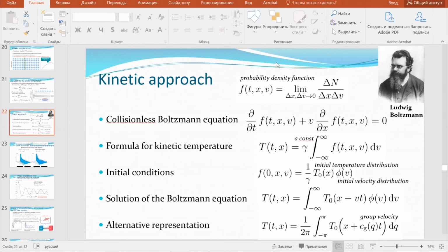You take the group velocity from the equation which we took from the long wave approximation. Then you go to this formula. Usually any perturbation in the system travels with group velocity, whether temperature, displacement, stresses or strains. The main question is how to find the main energy of the perturbation.